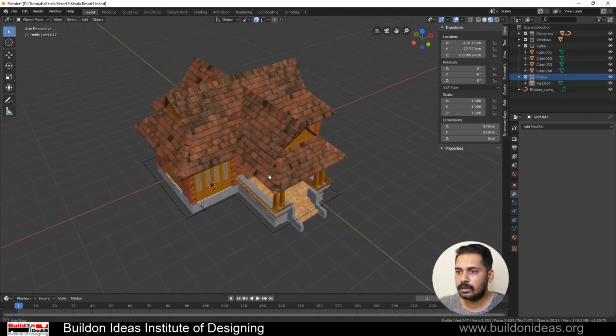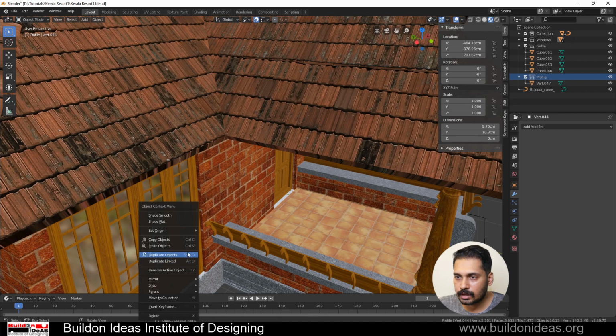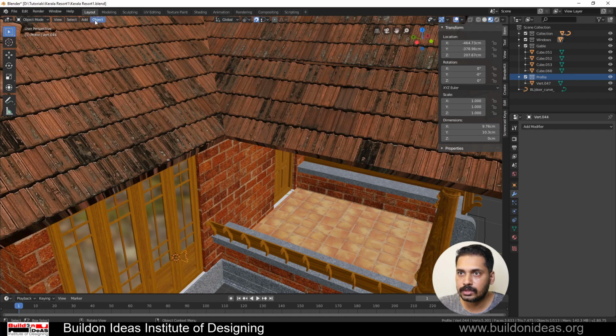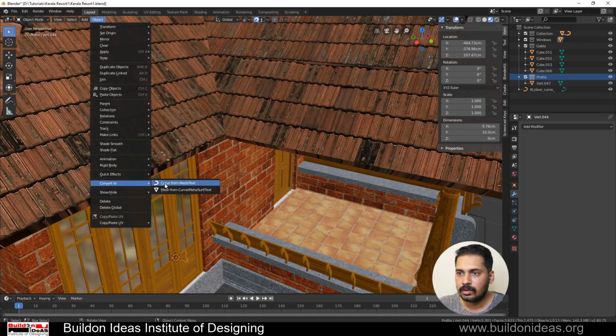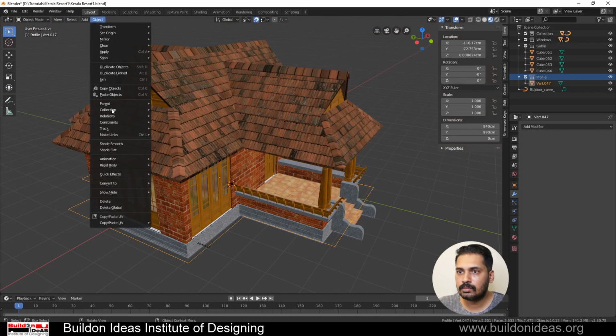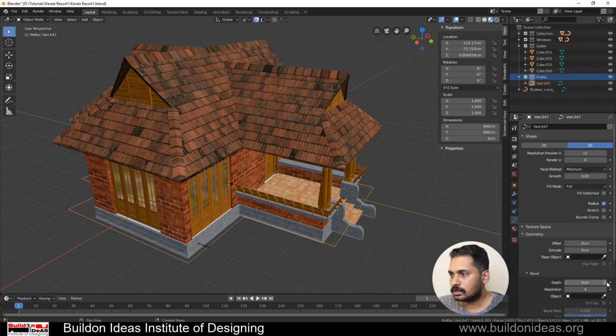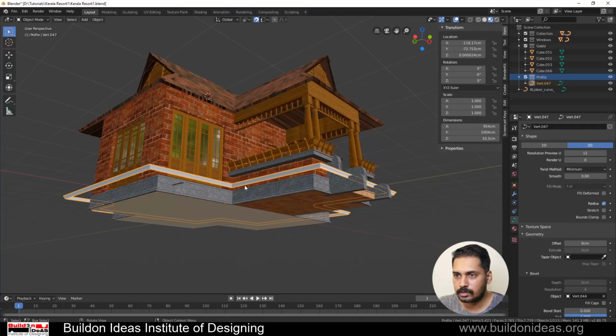Everything is on. I have a profile here. Select that, right click, object, and then convert into curve from projection. Select this, and then that also convert to curve from mesh. And now select this, go to the curves and then geometry, and then pick this object. You have the profile ready.